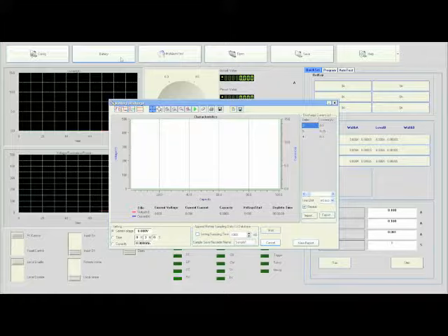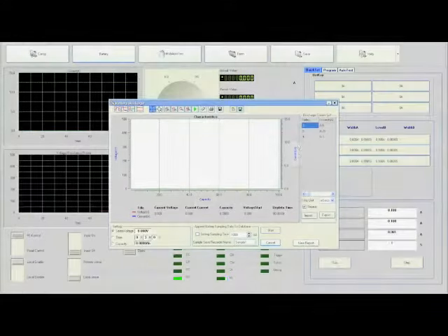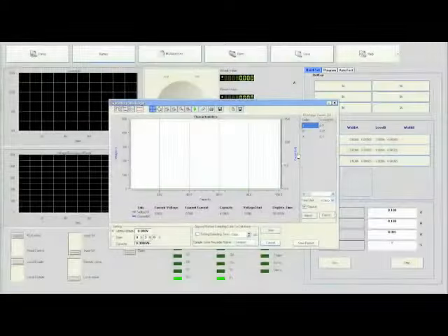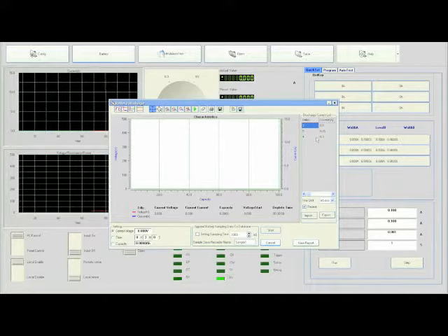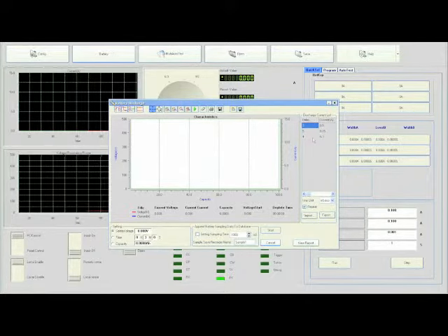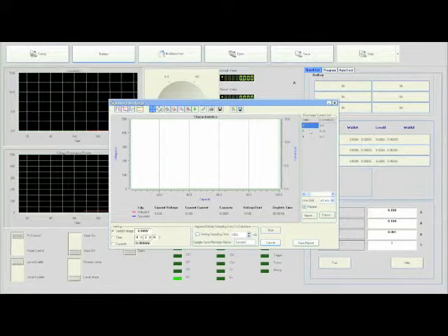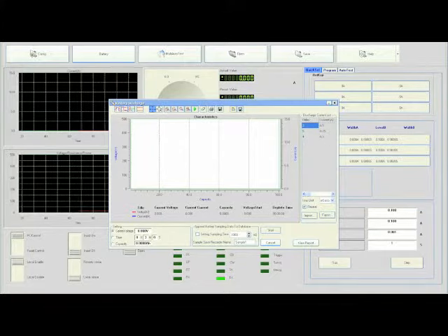The battery discharge window will open, and the main screen illustrates a graph with labels for voltage, capacity, and current. On the right column, a discharge current list is available for users to create custom discharge profiles for dynamic testing. Let's enter a few steps in the list for testing. Keep in mind the left column specifies delay and the right column specifies current.